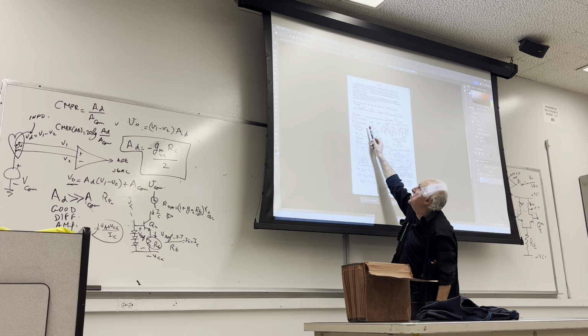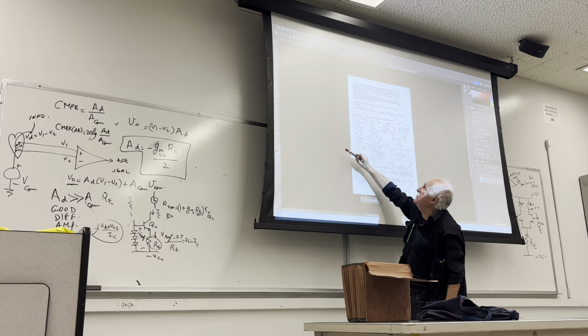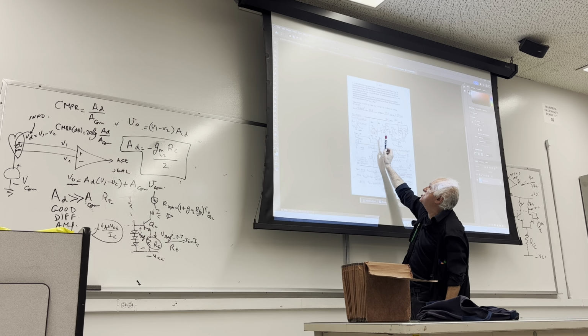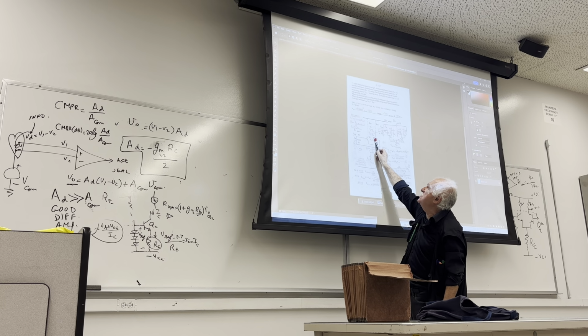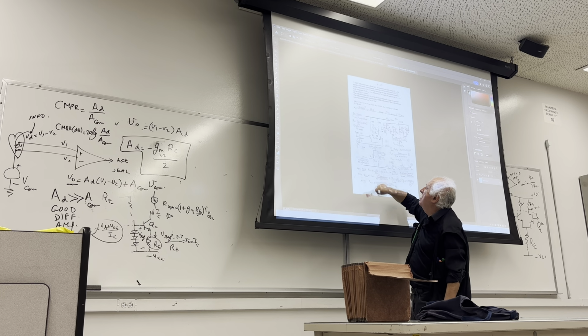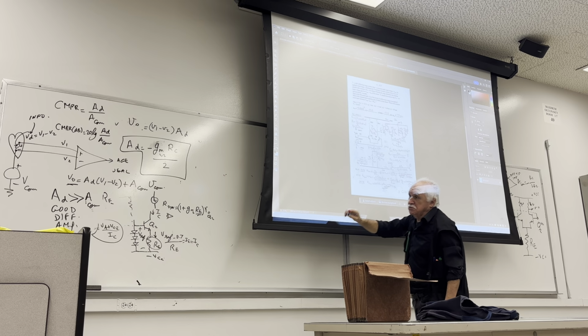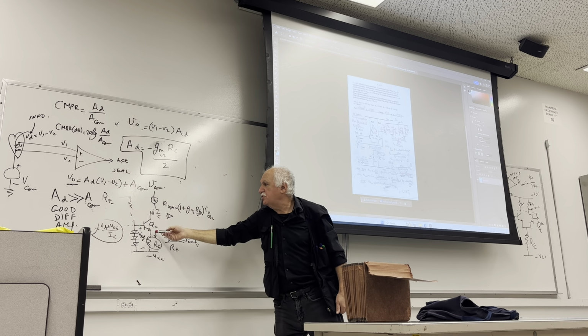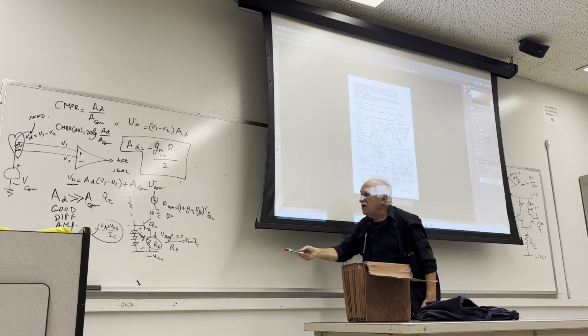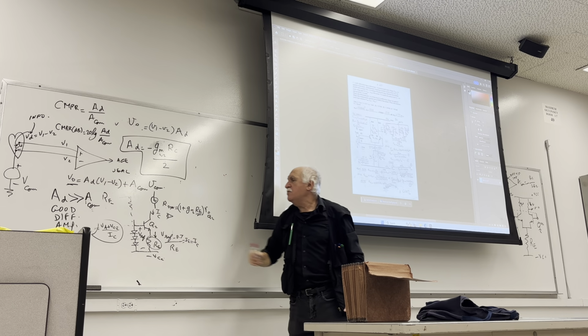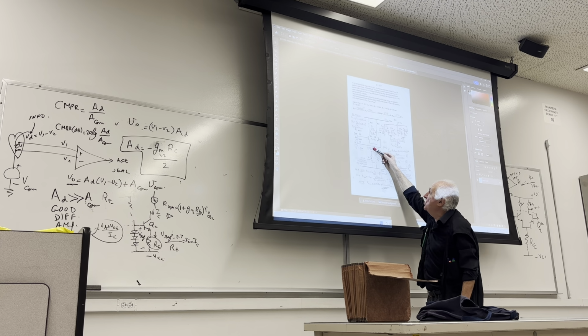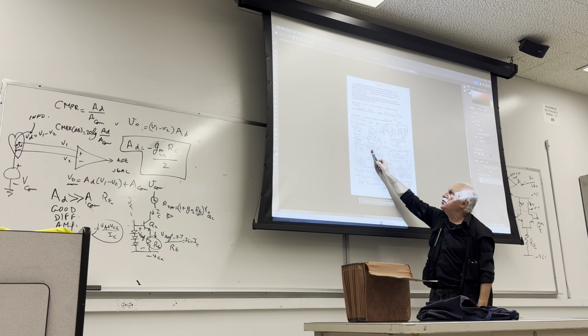So with that 0.55, you can calculate the GM of each transistor, GM1 equal to GM2. And if this was made with a transistor like Q3, for example, the GM of that, which is involved in here, should be calculated with this 1.1 milliamp.